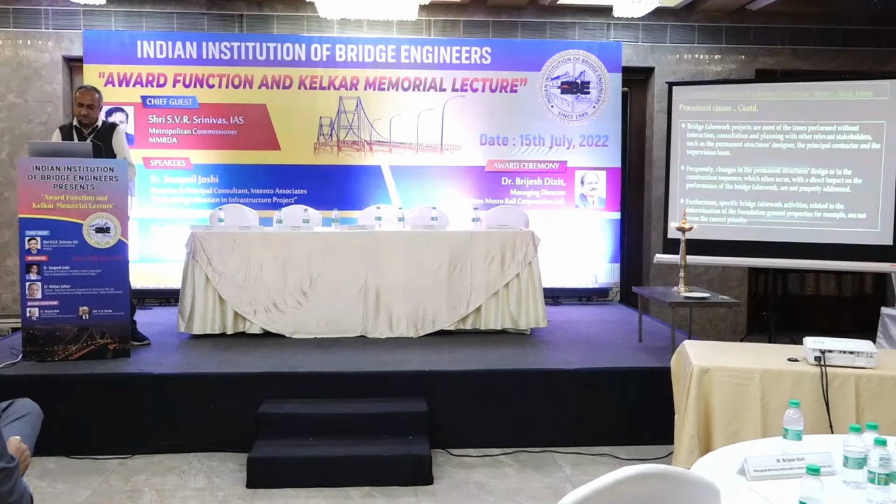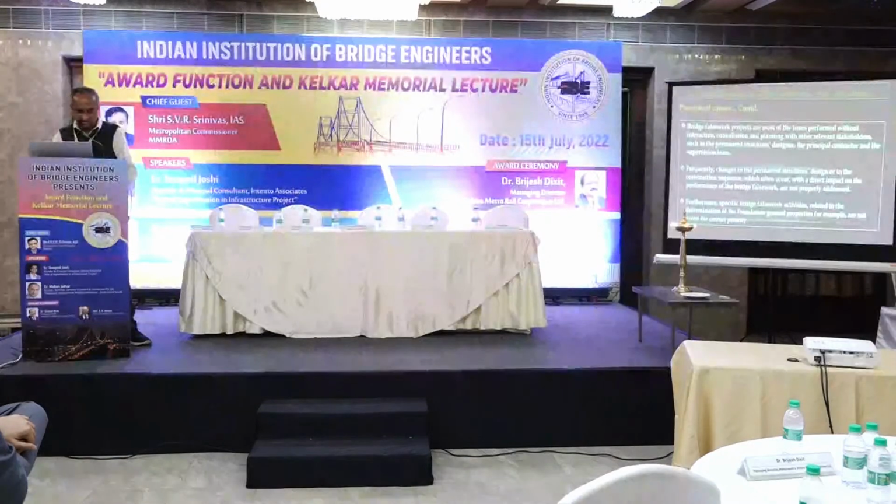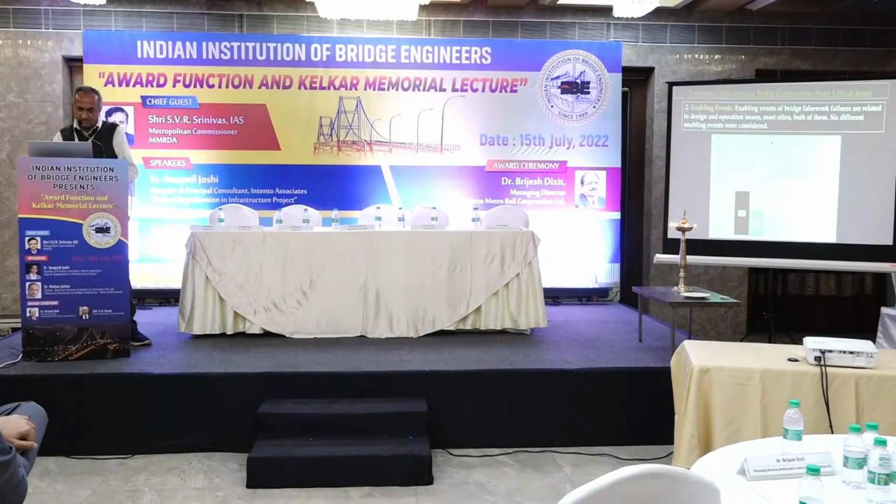In falsework projects, hardly any interaction takes place between the permanent designer and the other parties. This is one of the reasons. Frequently, changes in the permanent structures are not conveyed to the others, or changes in the construction sequence are not conveyed to others. Or there may be changes done at the site which are not conveyed to the corporate offices, and so on. So all these, inadequate ground investigations, all these are procedural failures.